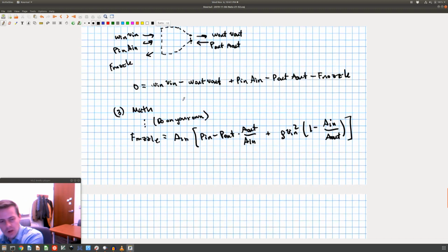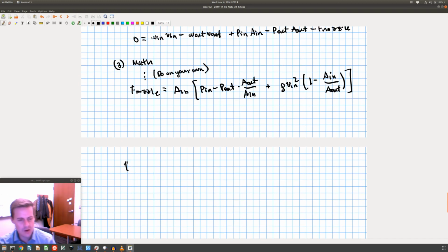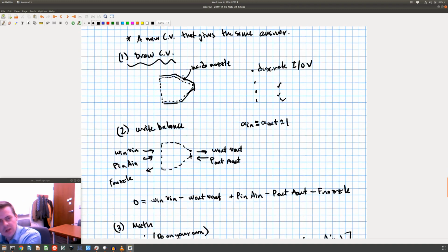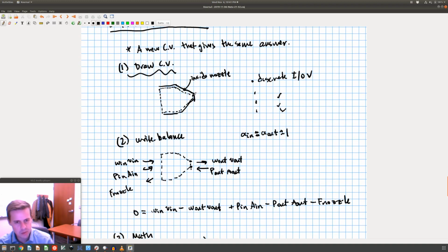So if I want the net force to include the atmospheric pressure, I need to have that be, let's make it minus because it's going to go in the negative direction, the F of the nozzle, plus atmospheric pressure multiplied by the stuff on the outside of the control volume that I didn't take into account, on this part out here that wasn't this internal piece.